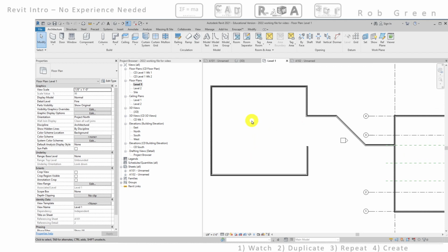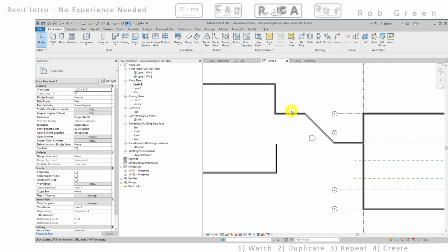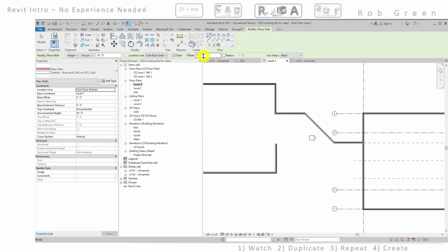I'm on page 53, and the textbook is going to ask us to put in these items down here. So it's going to ask us to draw the wall here, down here again, using an offset of a wall draw command. So wall, offset of 30 feet, pick line, and approach this wall and get ourselves an offset.